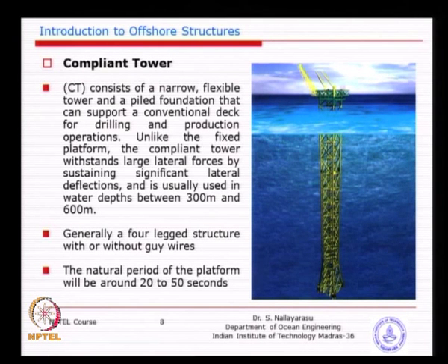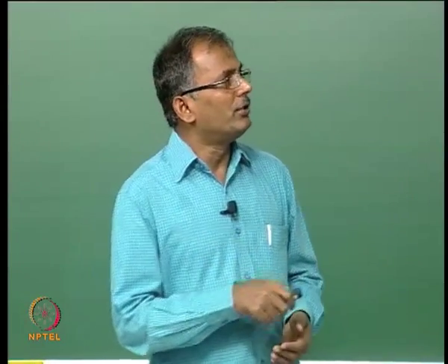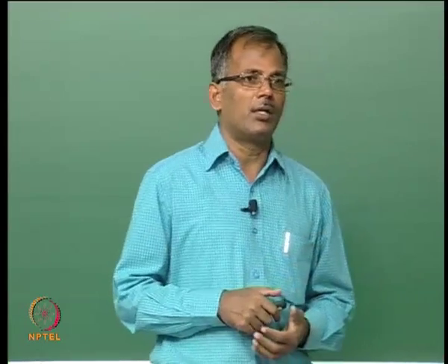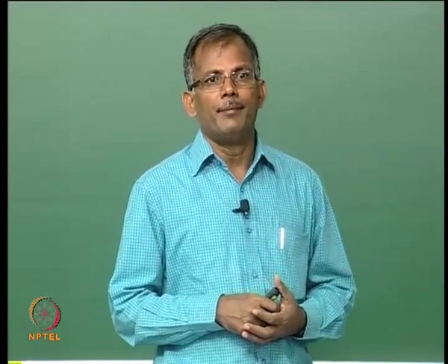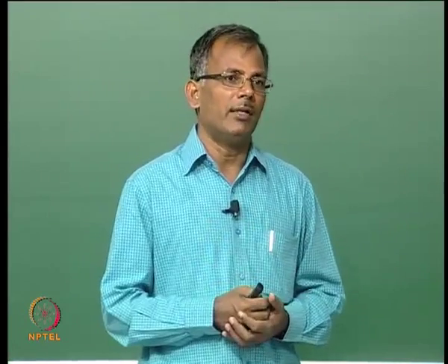So, there is a certain price to be paid, because not all equipment will work. A typical example is a drilling system. You expect a rigid platform for drilling. Now, this platform has a large horizontal displacement, typically about a meter or so. So, those drilling systems or equipment need to be modified in such a way that they are able to operate, otherwise they will fail terribly.